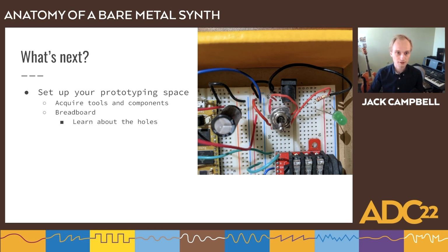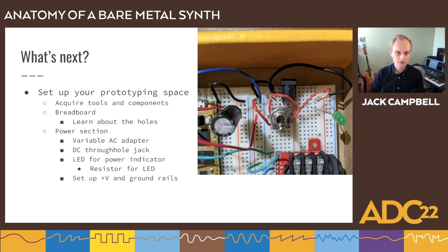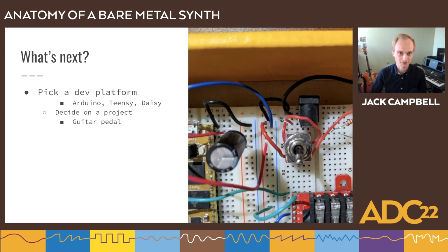Beyond books, I would recommend learning about breadboarding, and definitely set up a power section. I would call it a pro tip if I was a pro, but I'm not. So just a tip: set up a power section on your breadboard. I was lucky enough to have a DC power generator when I was doing this stuff in school, but you can set this up with some little components. Maybe I'll do a little blog post and a schematic on this, because for like $5 you can avoid continually plugging things in and out from the wall. You always know there's power. Otherwise, you'll always be wondering, why is there no sound? Oh, it's because the power doesn't work right now. It's very useful to have that for your sanity.